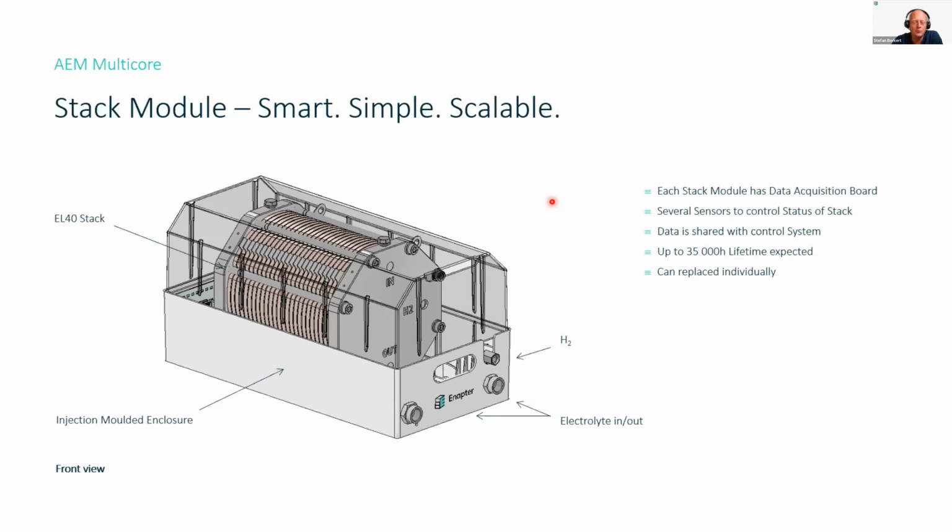And then we are getting to the famous question of combining electrolyzers with photovoltaic panels. So if connected to a 1 megawatt photovoltaic system, how does it work? What is the operating range? Can the multicore be operated continuously if the photovoltaic system power is changing between 200 kilowatt and the full megawatt? Yes, because we have a nominal operation flexibility of 3 to 105%. That allows us to follow the photovoltaic peaks.